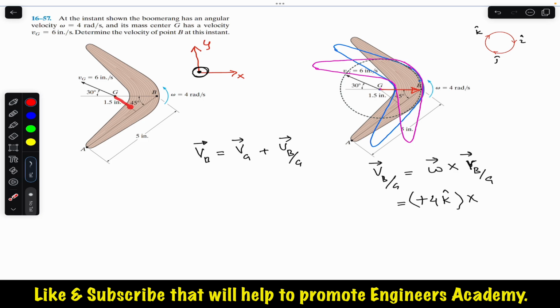And we are given this distance. This distance is 1.5 inches, and this angle is 45 degrees. So we need to find the magnitude of this vector which is from G to B. So how to find that magnitude? We are given this triangle, and here this angle is 45, this angle is 90, this is 45 degrees. Let me draw that triangle here. So this is that triangle, this is 90 degree, this is 45 degree, this is 45 degrees, and this is 1.5 inches. So this is the length of the magnitude of the R of B relative to G.